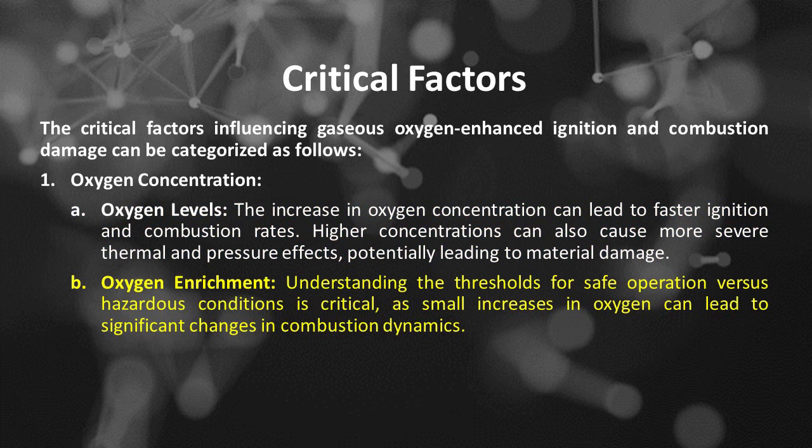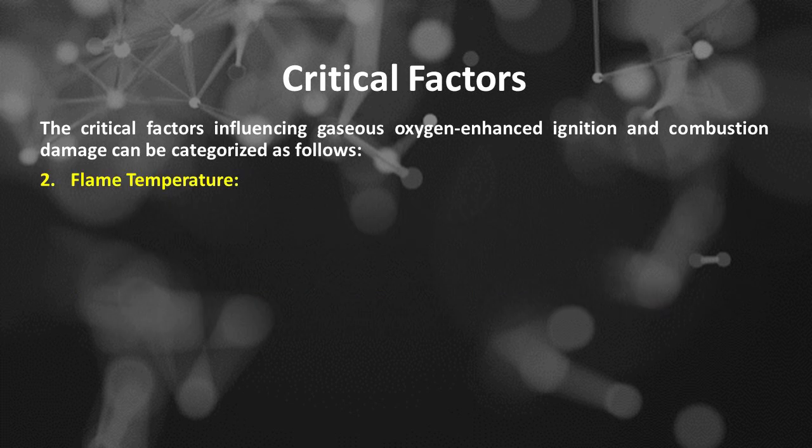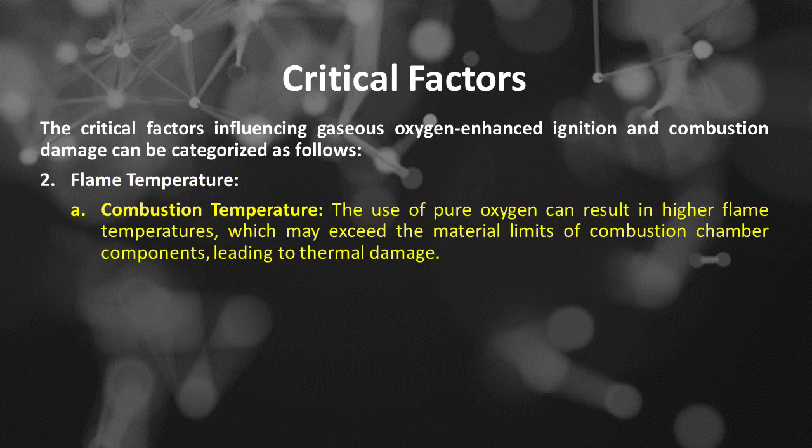B, oxygen enrichment. Understanding the thresholds for safe operation versus hazardous conditions is critical, as small increases in oxygen can lead to significant changes in combustion dynamics. Category number 2 of the critical factors influencing gaseous oxygen-enhanced ignition and combustion damage is flame temperature, which includes: A, combustion temperature.